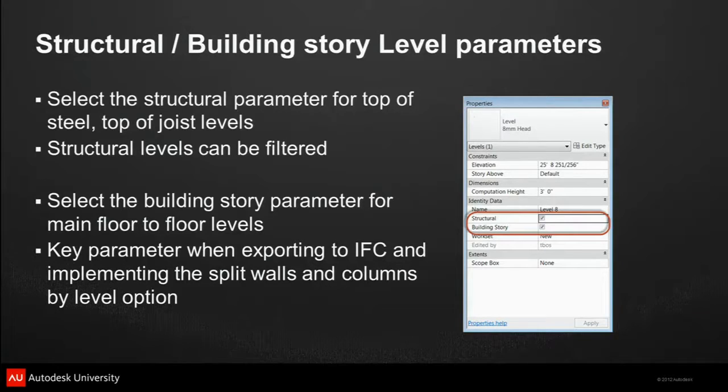Structural levels, building story levels. Did everyone see this when it came out? Structural levels. I was really excited about this. I thought that was cool. And it doesn't do what I thought it was going to do. My first thought is structural levels, I can make top of steel, top of joist, top of everything, and I could filter it out. That's terrific. I just assumed the architect wouldn't be able to see it if I called it a structural level. That's not how it works.